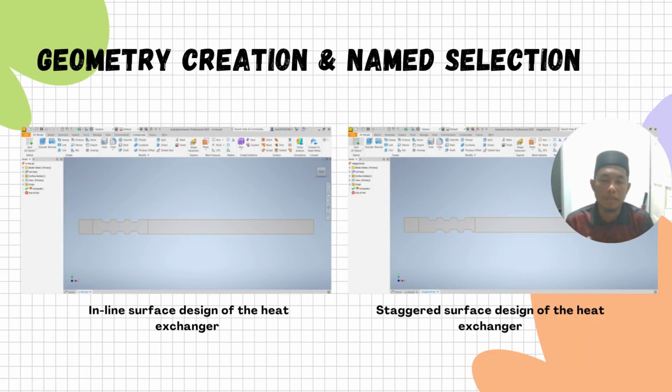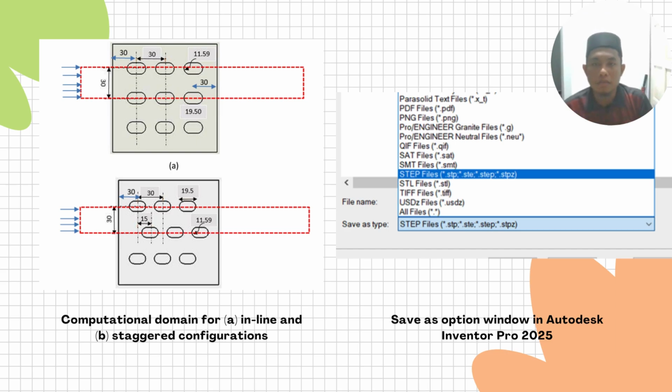So next is our geometry creation and name selection. So we designed our model in Autodesk Inventor 2025. The left side is the inline surface design and right side is the staggered surface design of the exchanger. So next, this is the computational domain for the heat exchanger. As we can see, the above and the below are inline and staggered configuration. So we save the file as step files in the Autodesk Inventor 2025.